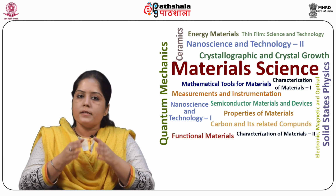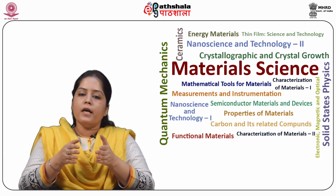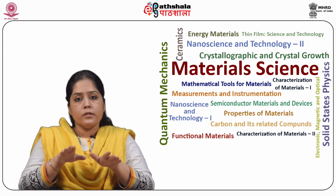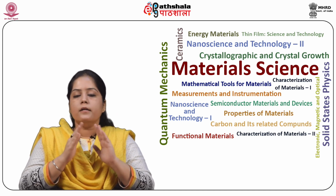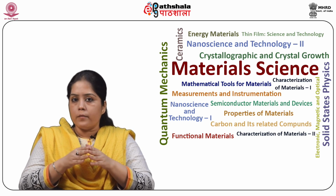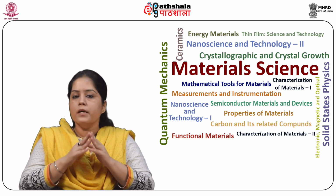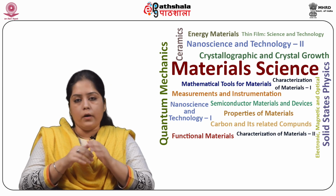They are easy to machine, they are weldable, and they can be precipitation hardened, but not to the high strengths that 2000 and 7000 can reach. 6061 alloy is the most commonly used general purpose aluminium alloy.